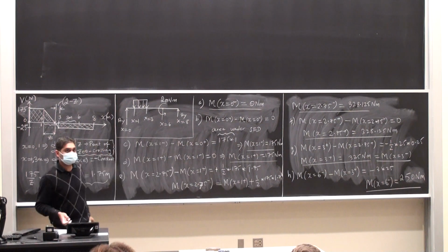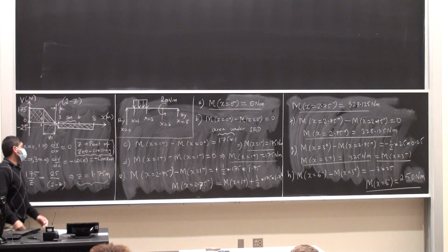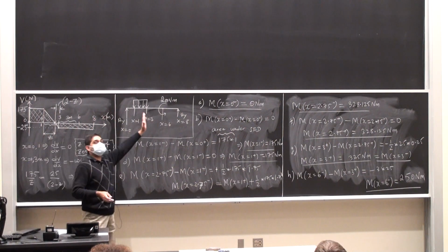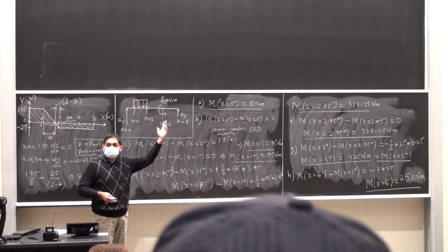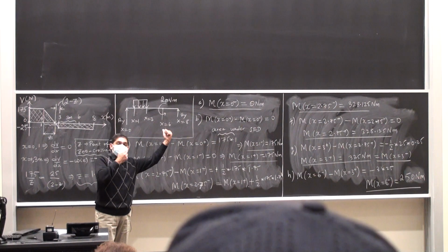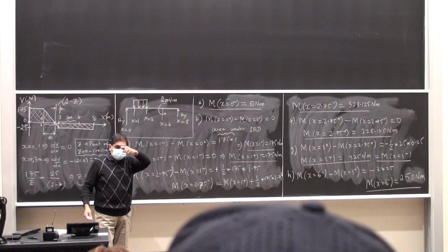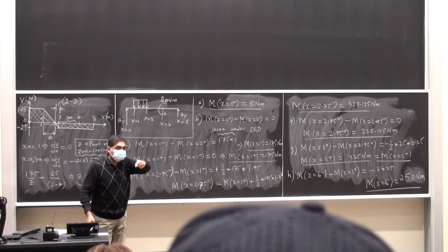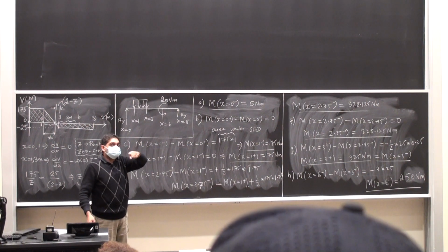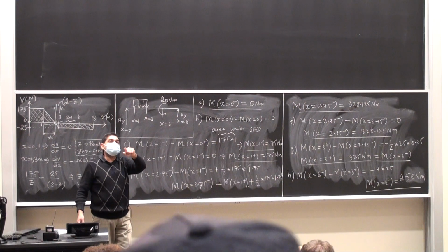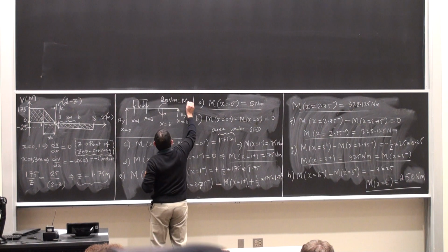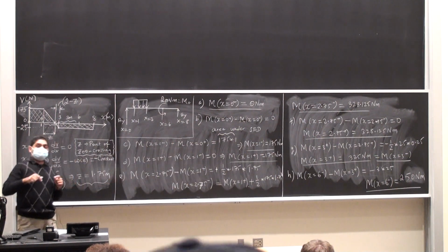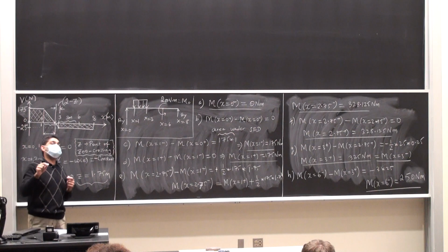Thank you. All right, are you all ready for the next event? That event is taking place at x is equal to 6 plus, because between 6 minus and 6 plus I am seeing a couple moment. This couple moment is in what sense? Counterclockwise. When we did our derivations, the change in the bending moment is equal to a positive M naught value, where if we call this as M naught, only when the applied moment was clockwise.